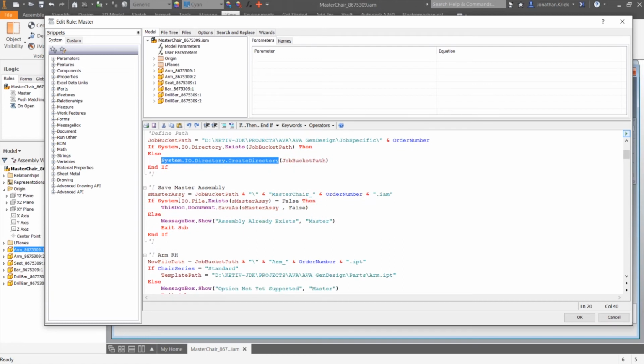The next part is really the key to this. It seems really simplistic when you look at the code, but you see what we've achieved. And there's actually a couple different ways to go about this, but this is the one that's most consistent. Again, instead of a folder exists, we're doing a file exists. And we're basically saying if this assembly has this path, this order number, which is going to be our new assembly. That's the new assembly we're creating. And obviously this path can change. We can have dynamic paths. Right now we're just offsetting that path with a specific order number off that original path. So we're saying if this file already exists, then that's fine.